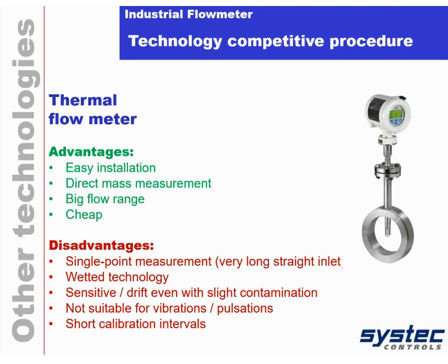And with a filter in before, to get them to a better accuracy, then they are getting much more expensive and also have pressure losses if you have flow straightener and filters. Wetted technology, that's clear, and that's the main devil. They are very sensitive to dirt and condensations.